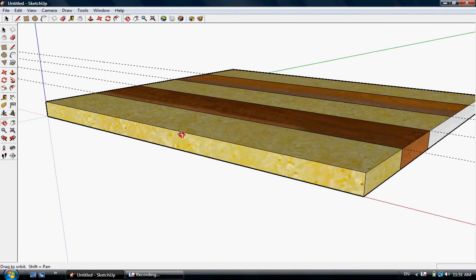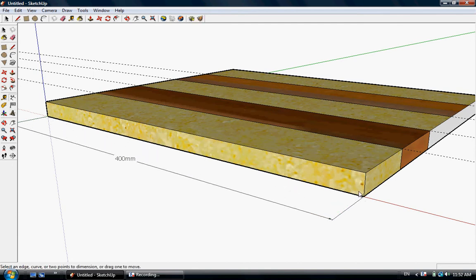It's not a very difficult drawing, but we're going to add some features to it, like dimensions. So when we click on our dimension tool, which is this one here, you can then click on an endpoint, another endpoint, drag it out, it tells me the length of it. I can always check the height as well, which should have been 19. Take that out, and that's fairly easy to do. Okay, put some dimension on there.